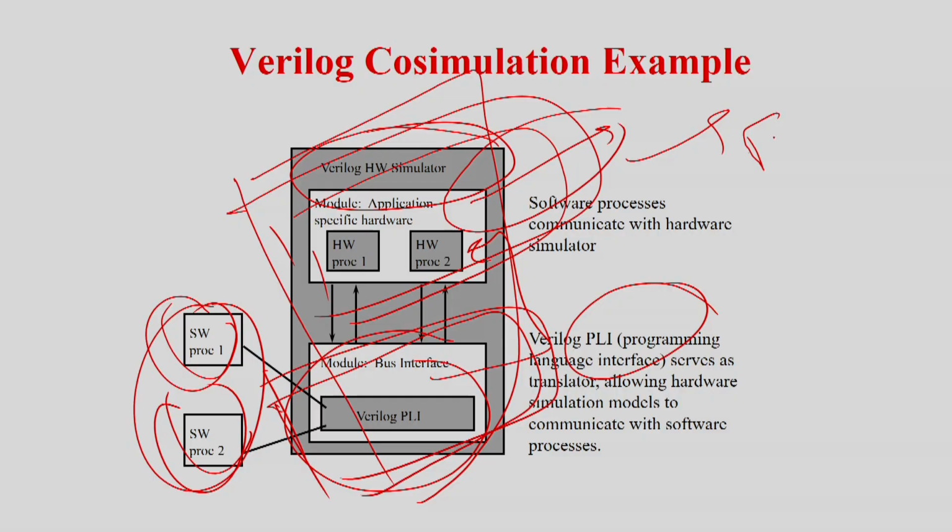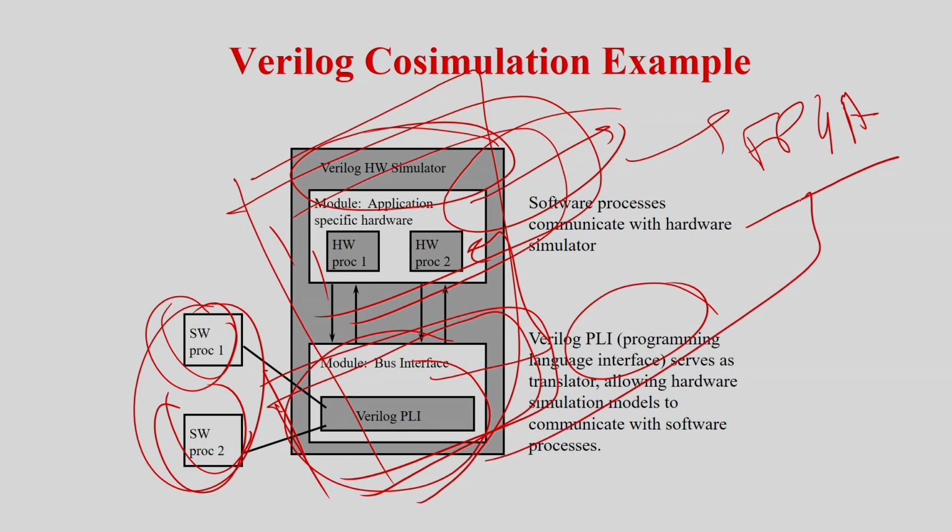So what is the solution? People try to take this and dump it into an FPGA. So it becomes a hardware representation. That is real hardware. I don't require to simulate anything. This is called emulation. Now you can directly download your software and test it.